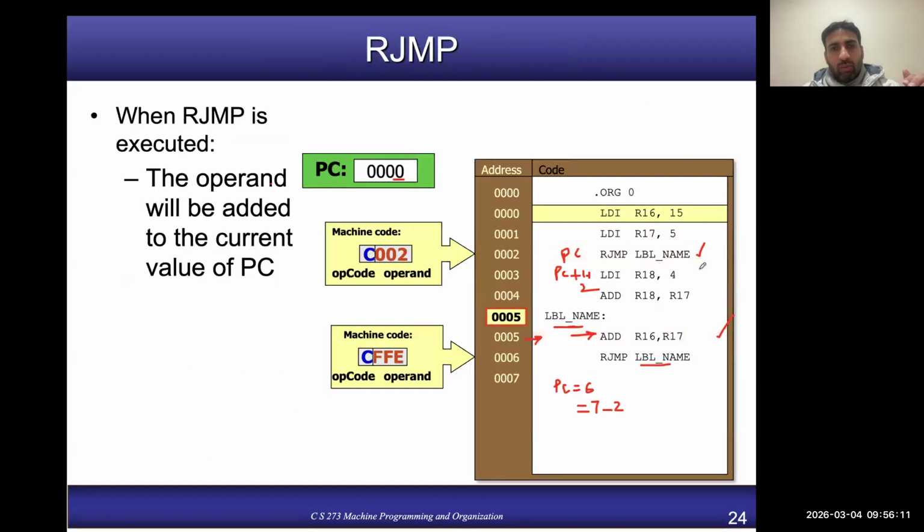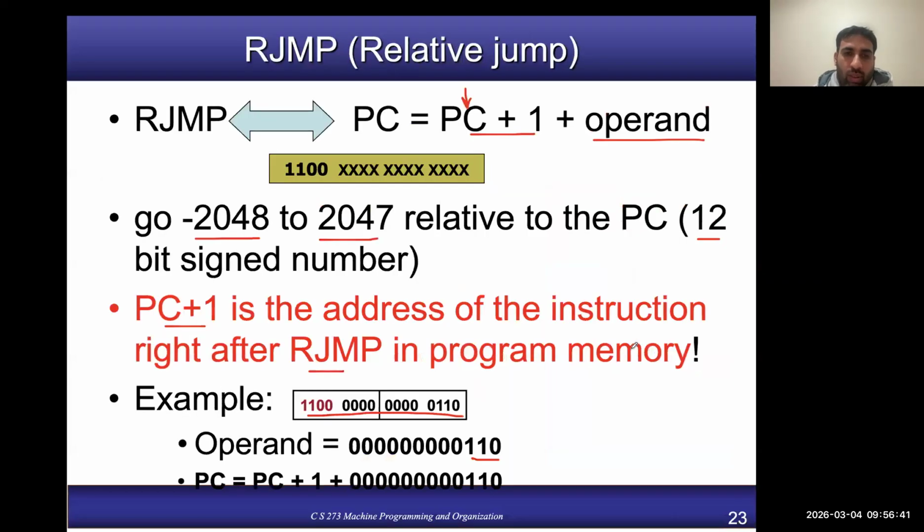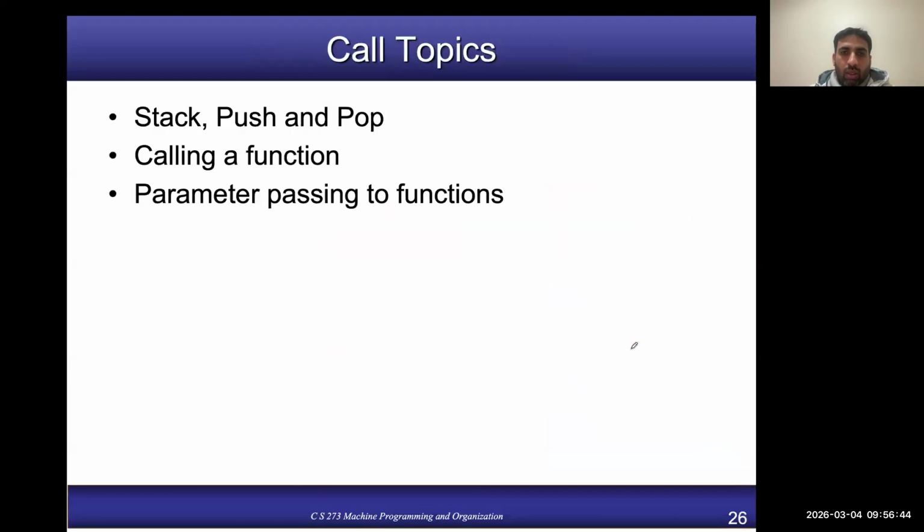So if I take you back, where is the jump instruction? Yeah, here, for example, jump label name, right? So every time you will go to the same place, or even for example here, jump label name. Every time you will go back to the same instruction, right? But if you are using IJump and in every iteration here you are modifying Z, right? So you will be going to a different address depending upon what you have placed in Z before using the IJump instruction. Okay.